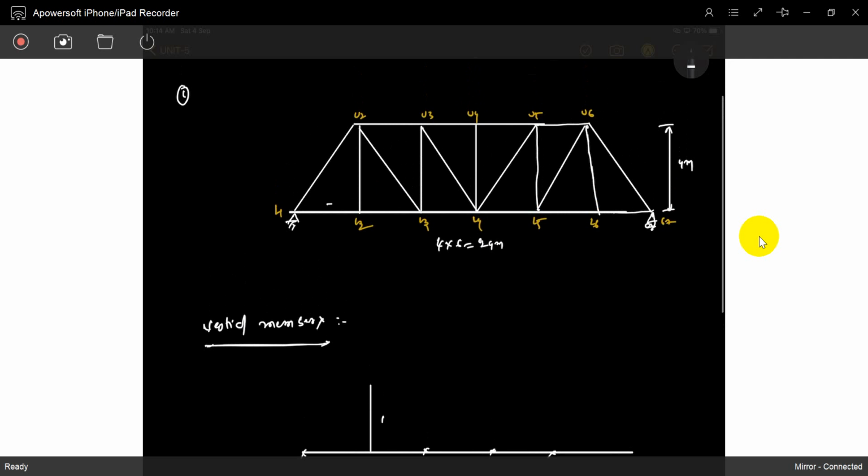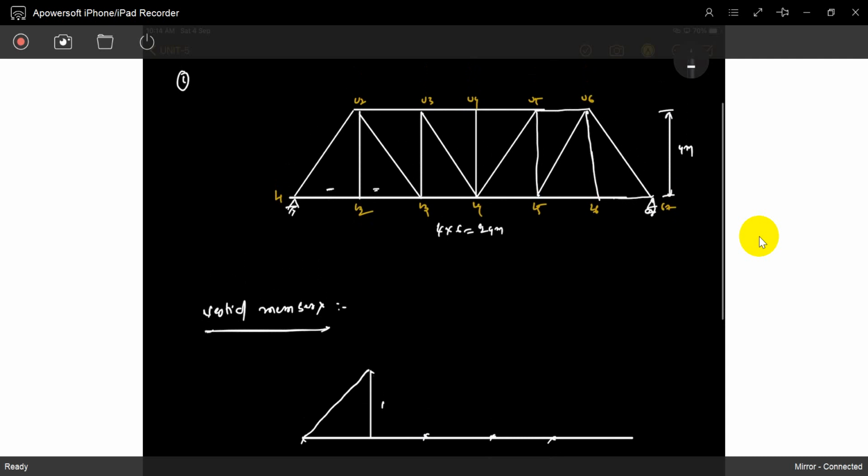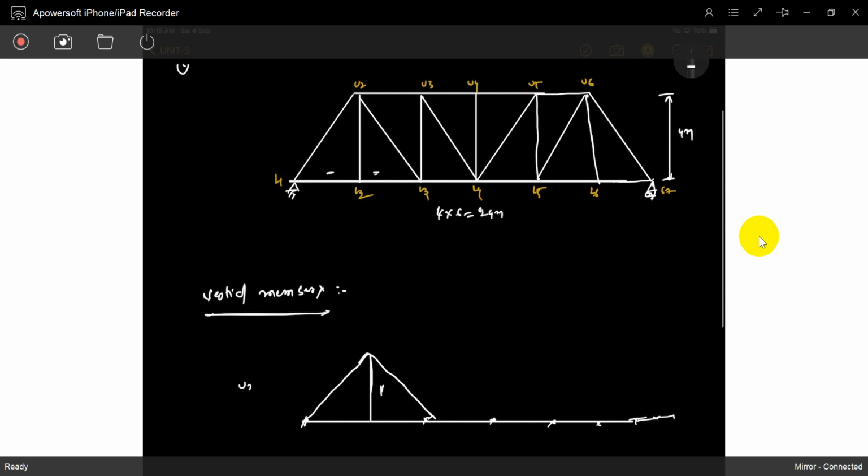But in between these, sir, in reality we don't calculate those positions. If you apply a load in between like this, it will take a small portion. In reality we apply the loads only at joints, and in between joints we don't take it. So just write down the influences: it's 1, it's 0, it's 0. The remaining everything is 0. So this is for U2, L2.